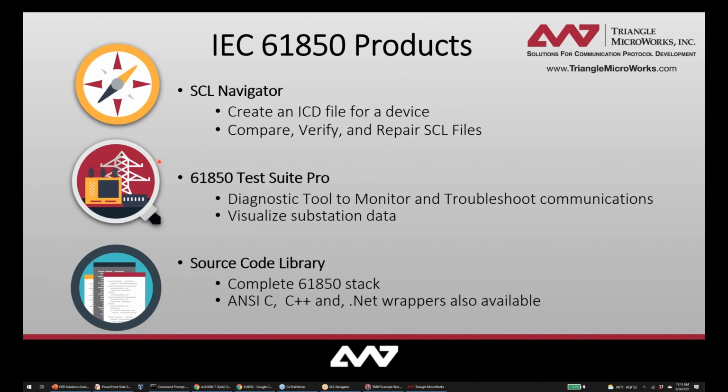It also has a functionality as an SCL verifier. We find that SCL files are not always perfect. SCL is an exchange format. One of the core tenets of 61850 is interoperability, so that we have devices and tools from different vendors that are able to interoperate with each other. To enable that, the SCL files are often passed between devices and tools of different vendors.